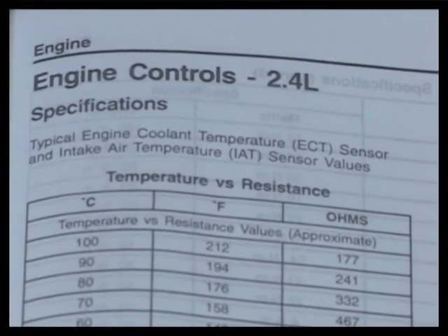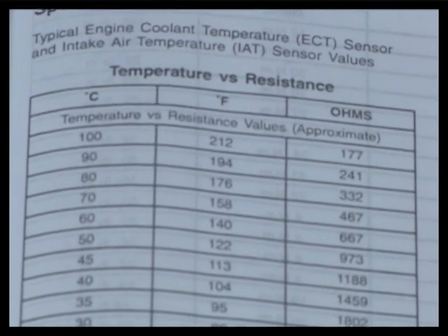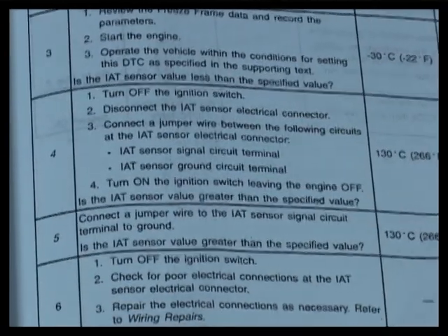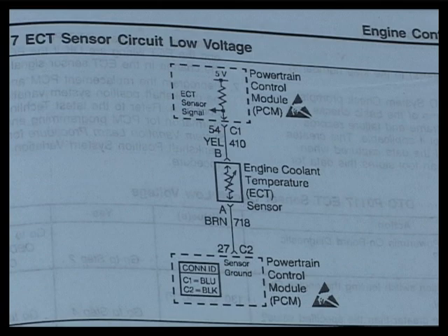This chart shows how sensor temperature affects sensor resistance. Charts are provided to help with trouble codes. Here's a coolant sensor diagnosis chart. It gives step-by-step procedures on how to test the circuit and the sensor to find the exact source of the problem.